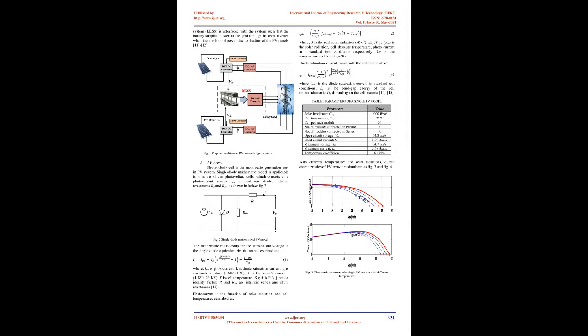Hence, an energy storage component is important to help get steady and reliable power from the PV system for loads or the utility grid, and thereby improve both steady and dynamic behaviors of the entire generation system 5-6. Because of its mature technology, low cost, and high efficiency, the Battery Energy Storage System, BESS, is used widely in distributed generation technology. BESS can be integrated into the PV generation system to form a hybrid PV/battery generation system, which can be steadier and more reliable. A basic grid-connected PV/battery generation system is made up of a PV array, battery, power electronic converters, filters, controllers, local loads, and the utility grid 7.